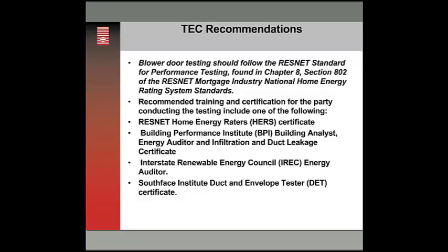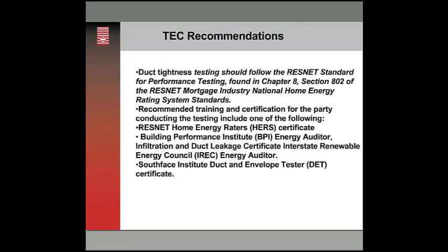ResNet, BPI, Building Analyst, Auditor, Infiltration and Duct Leakage Certificate. A lot of the DOE folks out there have the Interstate Renewable Energy Council, IREC, Energy Auditor, and then many people are testing to the South Face DET standard. And so on duct testing, again, same recommendation, follow the ResNet test standard. The BPI analyst may not get you there, so you might need the auditor. I was told there was one other BPI in addition to the IDL certificate that may qualify you to do duct testing. But again, the South Face and the IREC training would get you there.